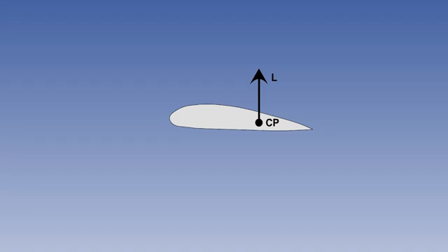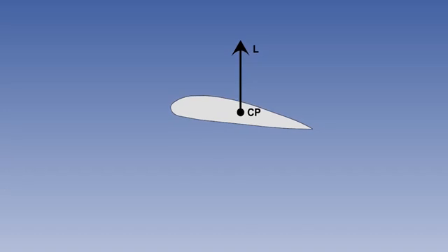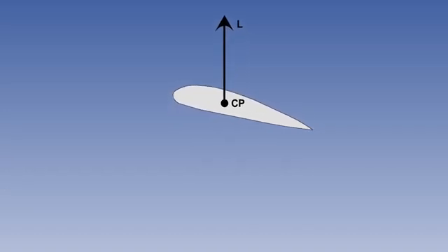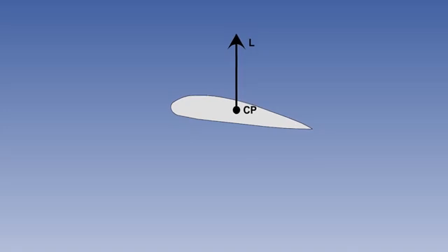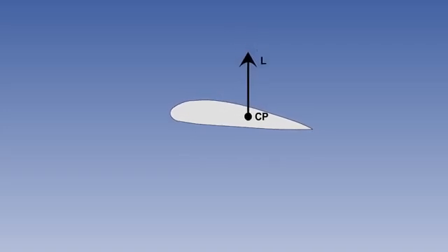There are two ways of considering the effects of a changing angle of attack on the pitching moment of an aerofoil. Either by measuring the changes in magnitude of lift through a moving centre of pressure, or, more simply, through a fixed aerodynamic centre. You know from the previous parts of this lesson that as the angle of attack increases, the CP moves forward and the magnitude of lift increases, and vice versa. This results in a changing force with a changing point of application.